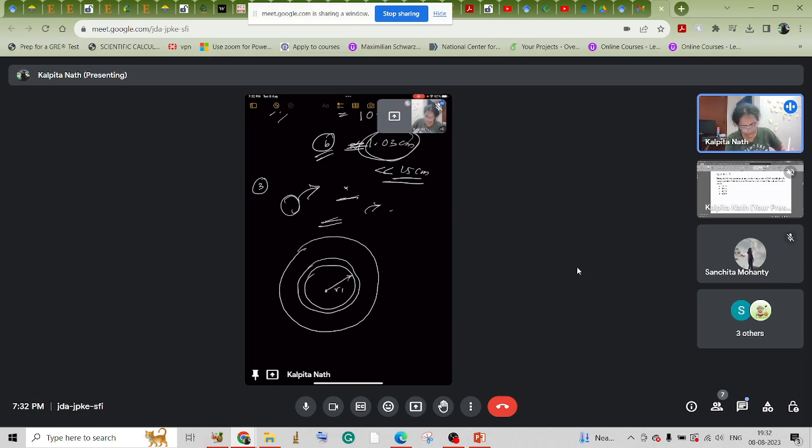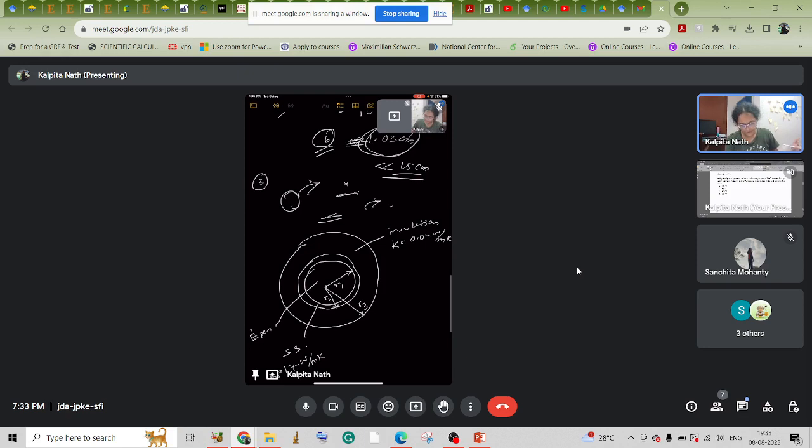So first, this is R1, this one is R2, this is stainless steel, right? And this is the insulation. Its thermal conductivity is 0.04 watt per meter Kelvin, and this stainless steel wall is 17 watt per meter Kelvin. Let us consider this as kW. Inside, energy is being generated from the pharmaceuticals, and let us consider this as the outer radius of insulation, and let us consider this temperature to be TS1.